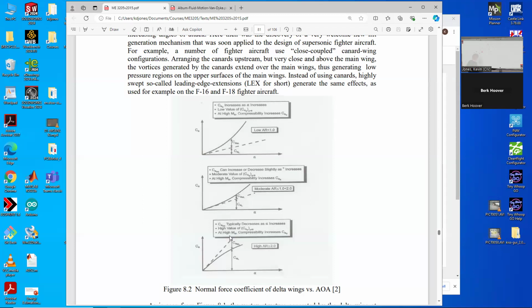If you think about a diamond airfoil in subsonic flow, when you start to put in lift, what usually happens to the stagnation point in front? Got some streamline that comes up. On a normal airfoil, you watch it travel down underneath the lower part of the wing, right? What happens here when you've got this sharp bit? Well, I think it's still going to try to travel down here, but the flow is not going to want to